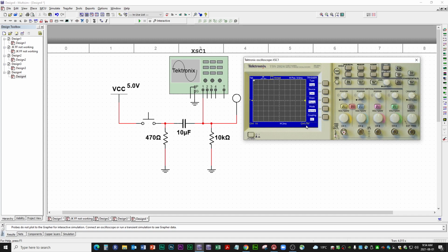All right, so let's just set this. Here's the channel 1 threshold level. So where's the level? Trigger level, right here. This number is going to change. All right, 10 millivolts is good. So it's going to ignore anything below 10 millivolts. And of course, if you're doing other experiments, you might want to set it to whatever you need.